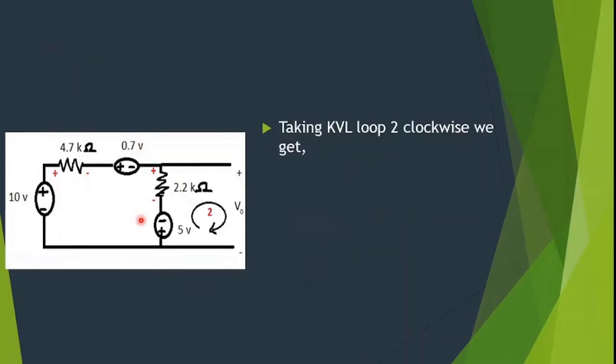now let's move on to the second one. Now we need to take a clockwise loop in here as well. So if we take that loop, what do we get? This is the equation we will be getting. This will be plus, because we are encountering the plus polarity first, and then minus IR2 here, as you can see, and then plus V0, this one. So this whole thing should be equal to 0, as I have mentioned in the theorem of KVL.